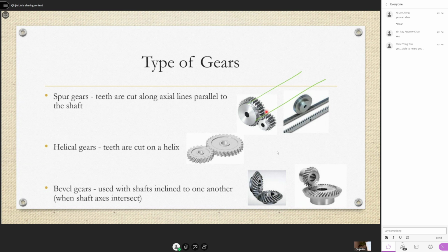The one that is attached to them usually will look about the same design, because you don't want to match this with another kind of gear that will cause a lot of wear or slip. So a spur gear, usually you will connect with another spur gear also. Sometimes it can look like that also. You have a track that will have a lot of teeth, and then a spur gear will be rotating, and either it will seem like it's rolling on the track, or it will seem like this thing is rotating on a spot, and then the track is being brought along in a certain direction.